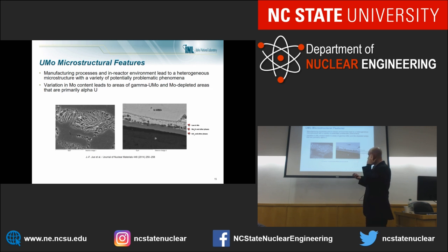examinations. Where this is important is that if we're starting the system with an excessive amount of dislocations, we get dislocation buildup much more quickly. This leads to recrystallization, and faster recrystallization leads to quicker deconstruction of the fission gas superlattice, which is another very interesting feature of these fuels.